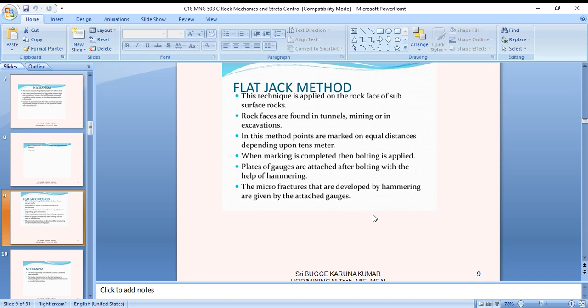Rock, however, is a material that is initially under stress. If, say, a strain gauge is installed on a mine pillar and the mined area around the pillar increases, thereby increasing the load, the gauge will indicate an increase. The strain measurement is relative, because the initial state of strain in the pillar was unknown.